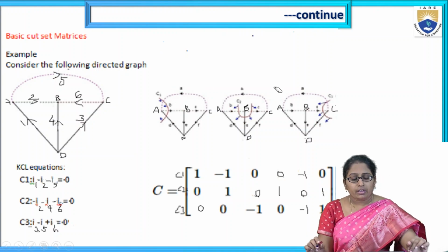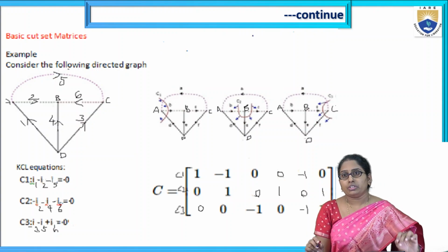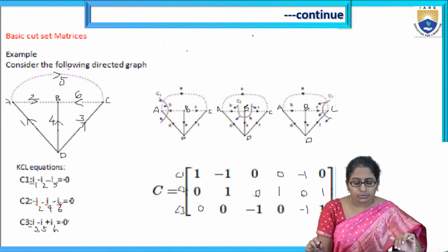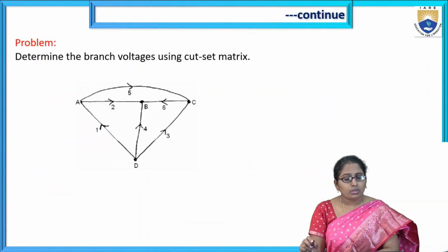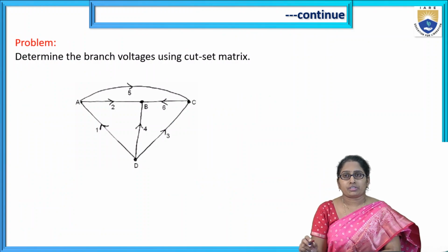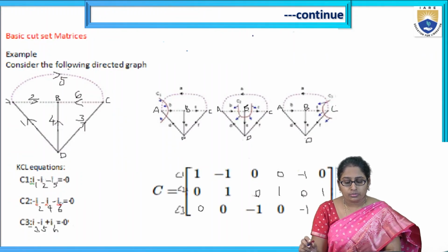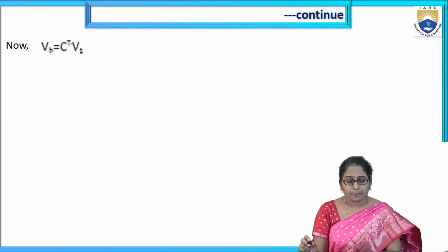Next, finally, according to the question, we have to determine the branch voltages, using this cut set matrix.